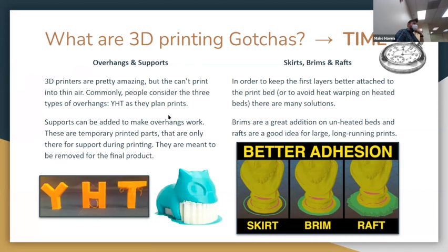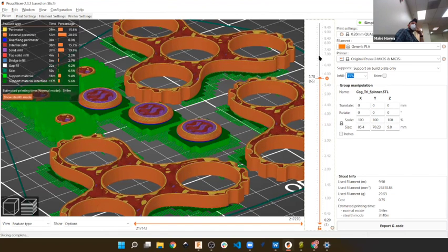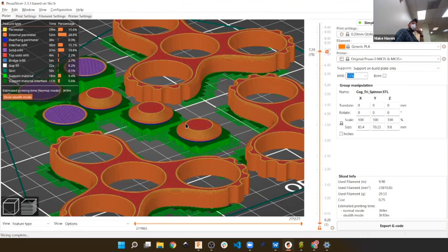Turn out better if you place them on the opposite space. You can flip them. I wondered about that. That might still tip over, but maybe it won't. No, you're totally right. And I was looking at the angle of this. So there's basically an angle for how much you can overhang, and I was trying to decide if those were 45 degrees or not. My judgment was that they were a little too overhung for it to be okay. But I think if I flipped them over, it might be fine. Maybe I should do that. This was good for a demo though.